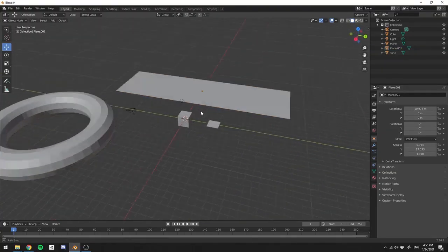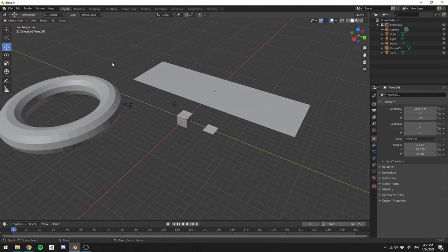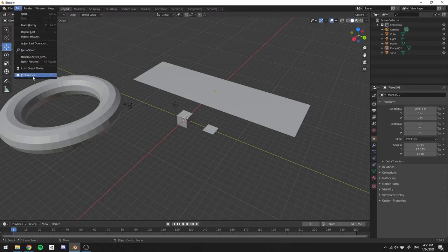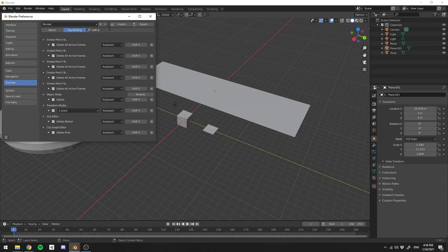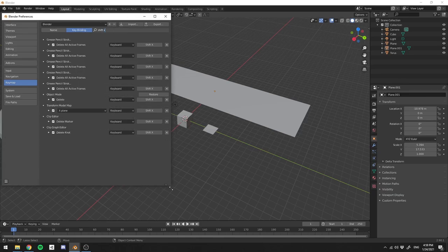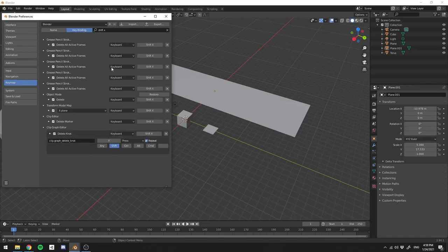So this is pretty much it for this lecture. Super easy to add objects. I showed you how to bind the keys. You can bind everything from the Blender hotkeys, just go to Edit, Preferences. For example, if I want to search what is linked to, for example, X or Shift and X, you can find all the keys that are bound to Shift and X. And if you want to copy something, you just copy this information, add it into the industry compatible keymap, in the same place, and just bind it with the same hotkey, and it will work just like a charm.